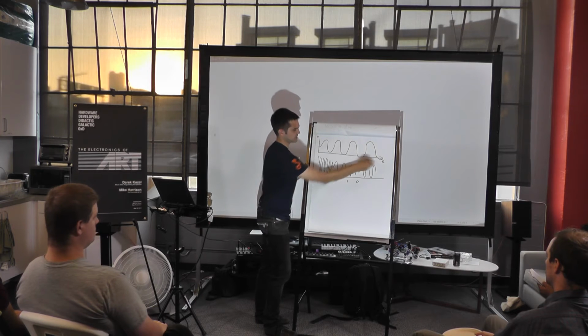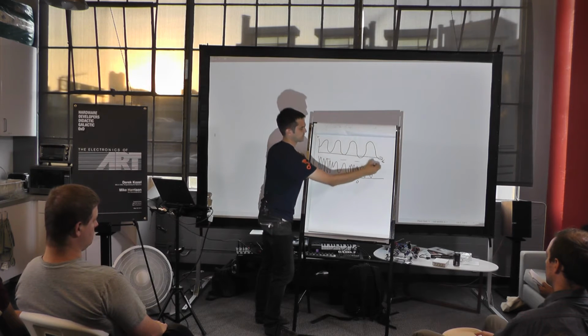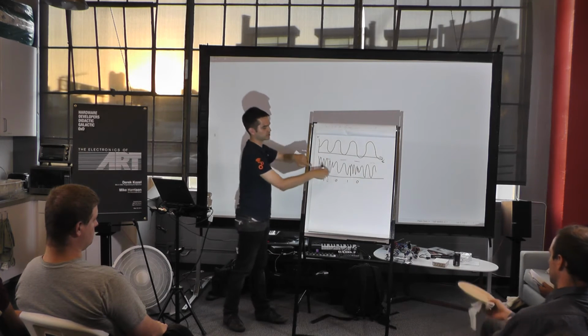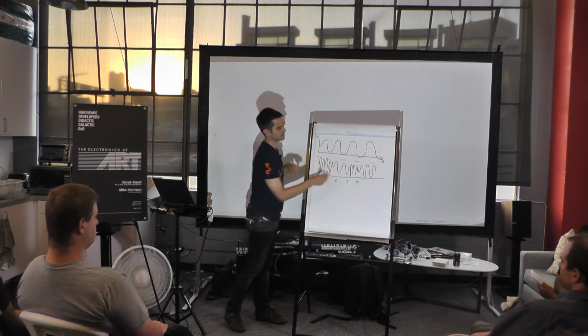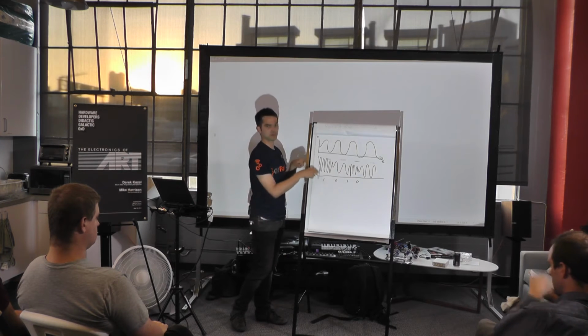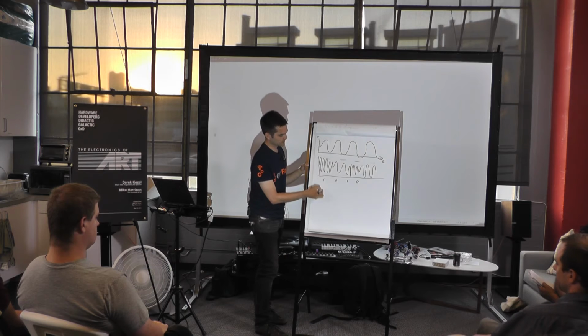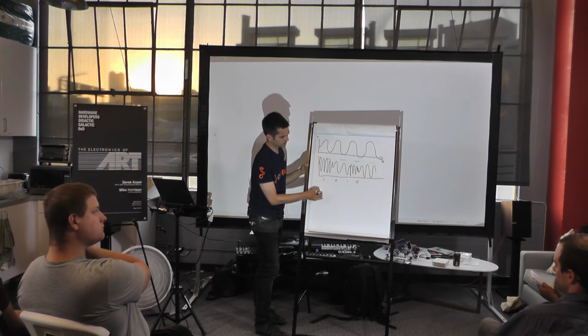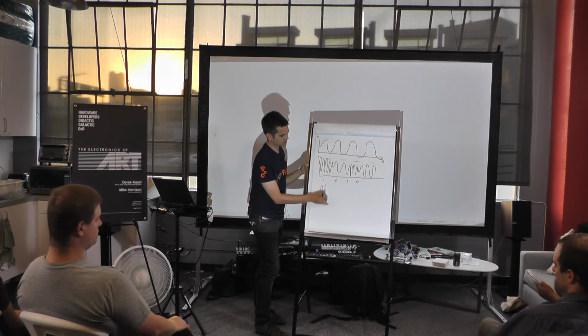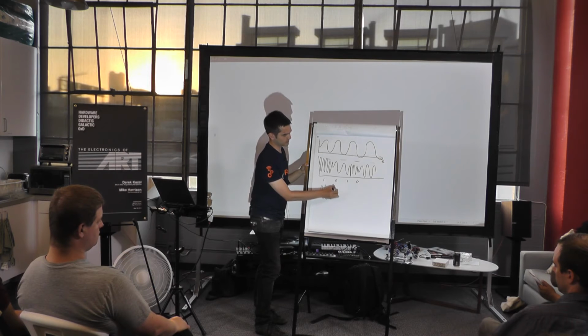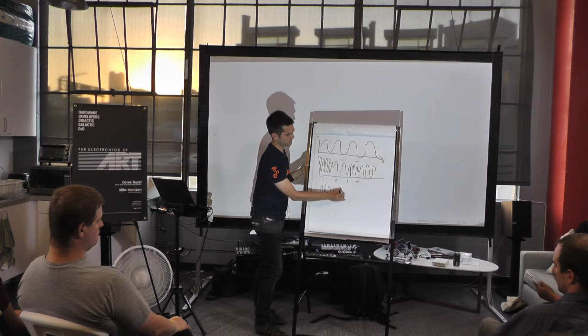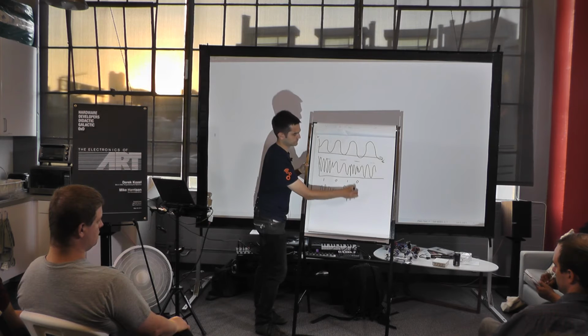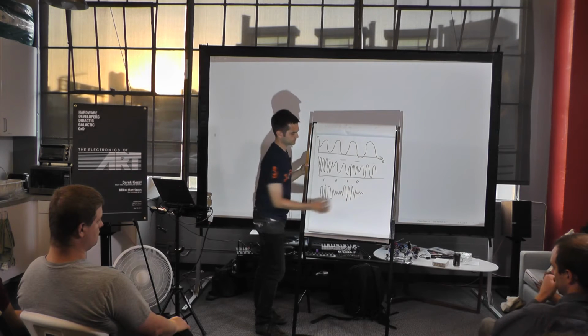And that should all be the same height, because we would call that a constant amplitude signal. We're only changing the frequency of the sine wave. So that's the basic FM. Then if you had amplitude modulation, maybe 1 is the really tall signal, then you have a much smaller one, and a tall one again, and a small.